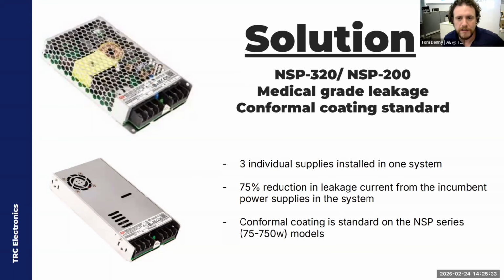Exactly, because their filtering has less of what we call Y capacitors and more inductive filtering, which is in series with the line. That allows the EMI filter to work, but not have as much conduction to ground. It's medical grade leakage, but they're still industrial rated power supplies, so they work for this application. As a matter of fact, this product has certifications for industrial, medical, household appliance, and also 61010, which is the industrial test and measurement standard. So quite a good solution for us to be able to help these clients.